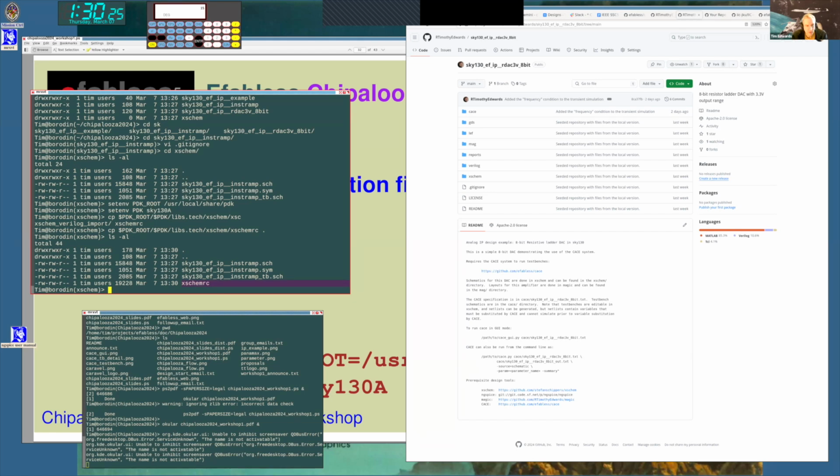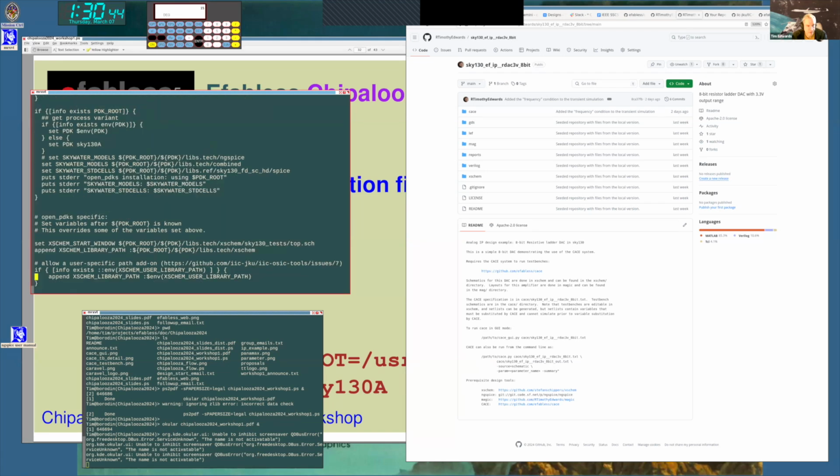There's one other thing I want to do, and that has to do with the fact that I'm going to have schematic files in two different directories, one for the characterization and one in my local file for what I'm doing. Since I've done this in a slightly oddball way, I have made all of my symbols relative to the root directory of my project.